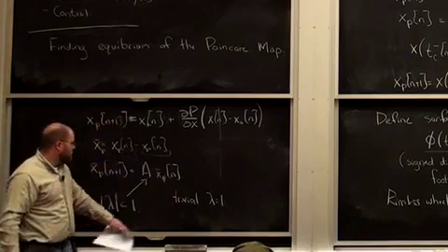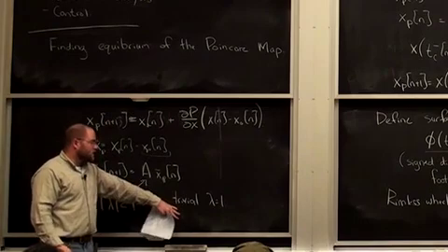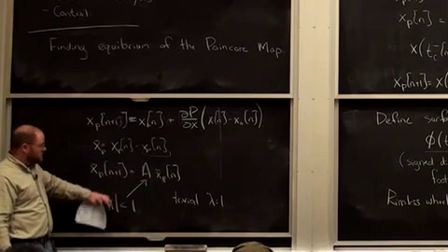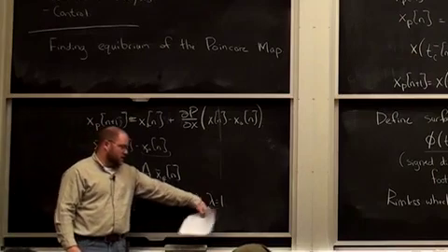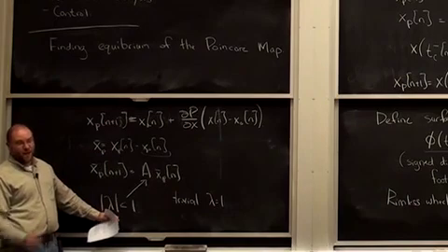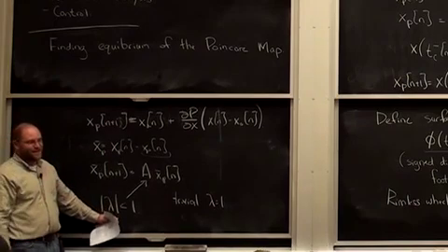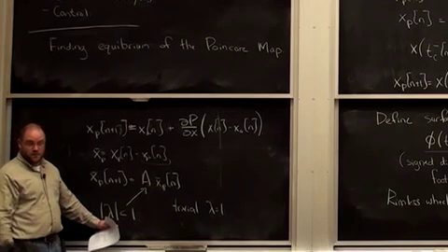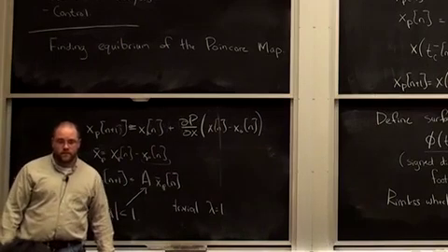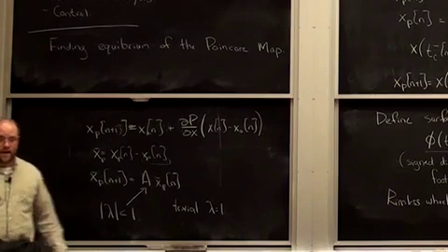The way I describe it in the notes is that for stability of the periodic gait, you ignore the first eigenvalue of 1. The rest of them had better be less than 1. I want only one direction that doesn't reject disturbances. What happens if you have two lambdas equal to 1?